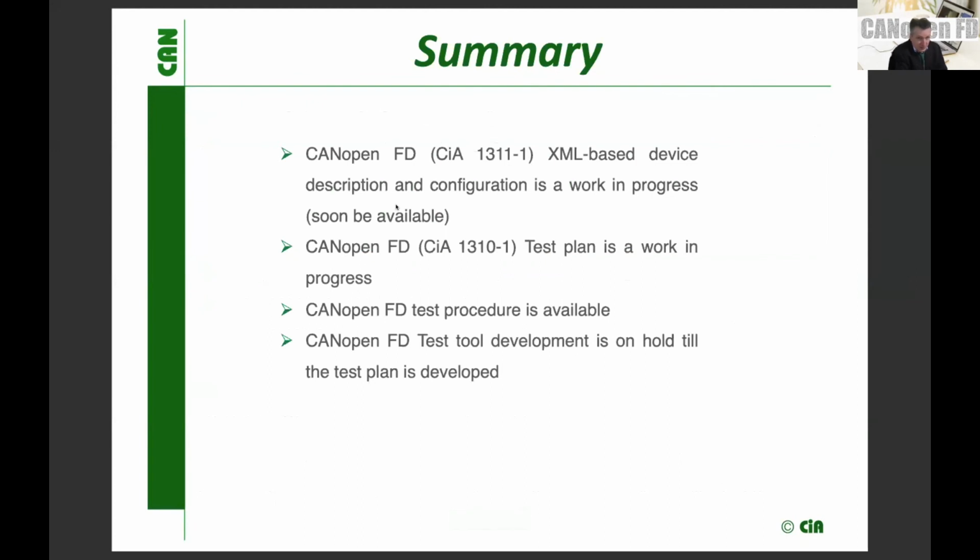Then you learned a little bit about what we do with device description. It is XML based, contains very necessary features and requirements for the devices, how they should be described based on the 1301 specification, and this specification you need, 1311-1, provides not only device description, but recommendations and information about the device configuration, and also one small example of how the XDD device description generated by an XML-based tool should look.